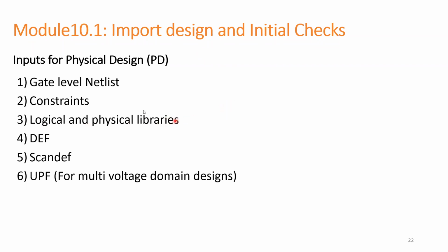Using this information, whatever cells we are using in the gate level netlist, for each corresponding cell we should have the logical timing information and physical information. Physical information means LEF should be there for each and every cell. DEF is design exchange format.